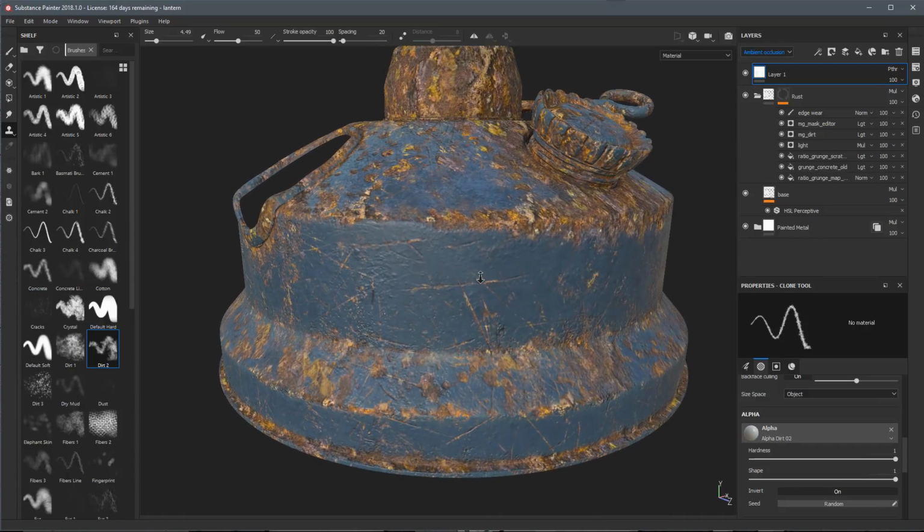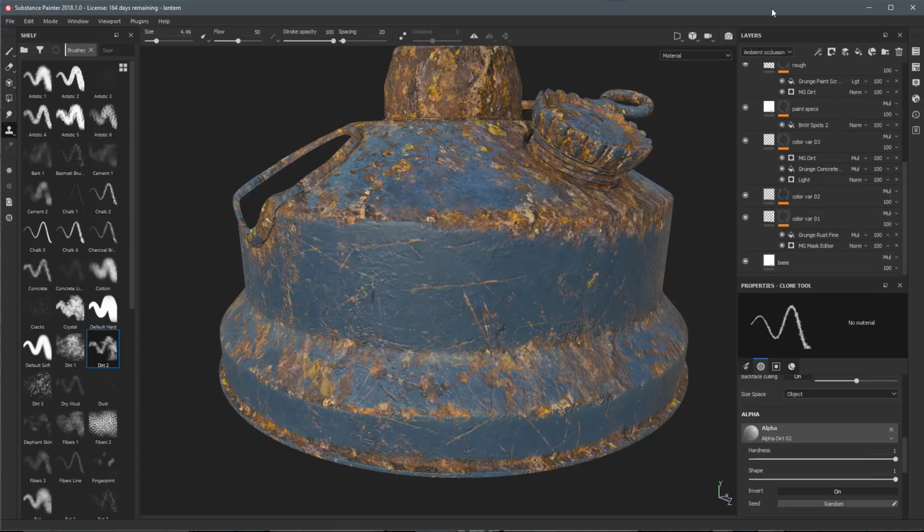Okay, so what's also really interesting about how the clone system works here in Substance Painter is that it's completely non-destructive. So for example, let's say that we have now done our cloning operation. Here, this is our layer. Let's say this is cloning, so we've done some cleanup work after the fact. Let's scroll all the way down here, and let me set this to my base color just so I could see the color thumbnails.